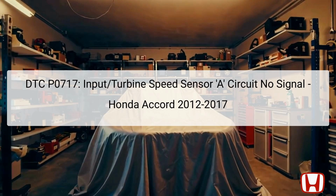This presentation addresses the diagnostic troubleshooting process for DTC P0717, which pertains to the input or turbine speed sensor A circuit no signal issue found in Honda Accord models manufactured between 2012 and 2017. The error specifically indicates a problem within the electrical circuit connected to the transmission's turbine speed sensor, an essential component for proper transmission operation. The turbine speed sensor measures the rotational speed of the torque converter's turbine, which is vital for proper transmission shifting and control.